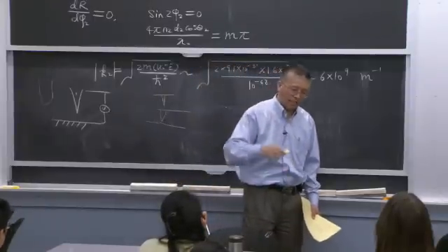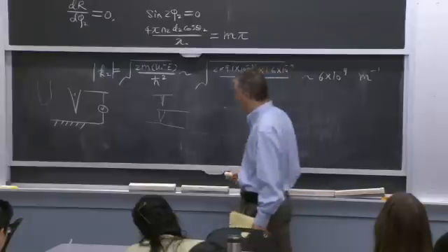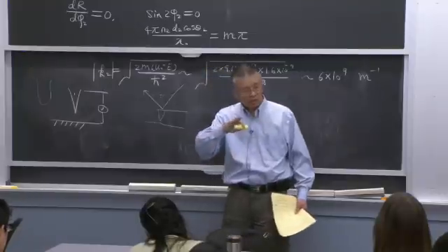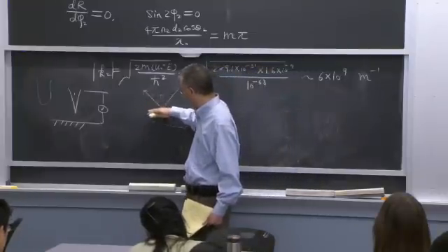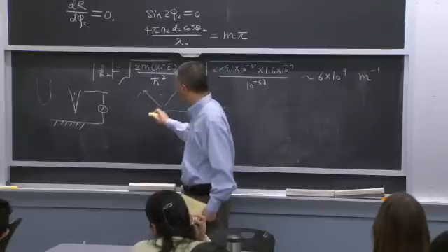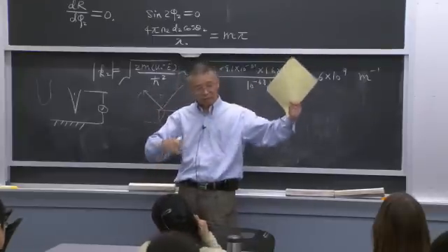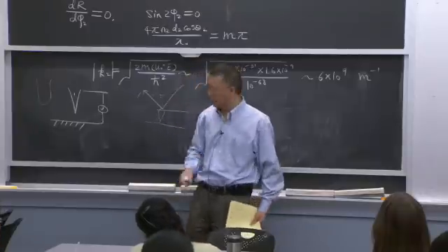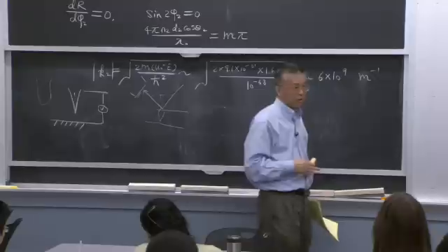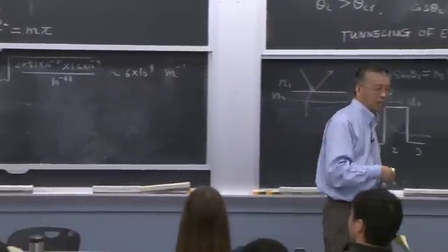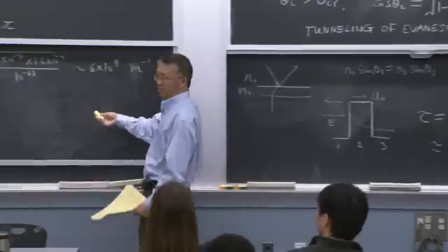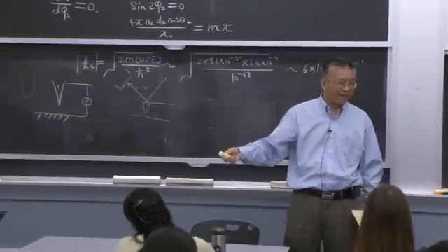It was later on people say, okay, there's a much easier way to do it, and that's by optical deflection. Because optical deflection is magnifying the small change in the height into angle. Angle times this distance is a magnifier, because for that small angle, if you magnify the distance, you put a position detector, and you measure this voltage change at different positions. So that became much easier to implement. You see, you've got to have your knowledge and got to be creative. Sometimes you also have to have a break, right?